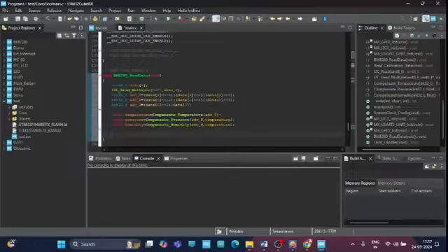Okay. So these functions use the raw data ADC_T, ADC_P and ADC_H and the calibration data to calculate the actual temperature, pressure and humidity. Now let's use printf, temp percentage 0.2f.